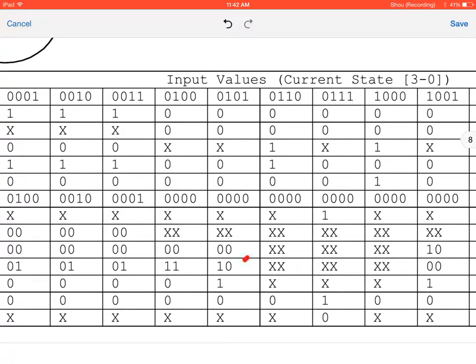1011, we have these values we're adding. So we have one, we're adding these together. So this is some sort of I-type instruction. In this case, it's going to be your load word or store word calculation. Here, we're having branch and jump. So we have a bunch of don't care values here. Right, we have PC write condition set.